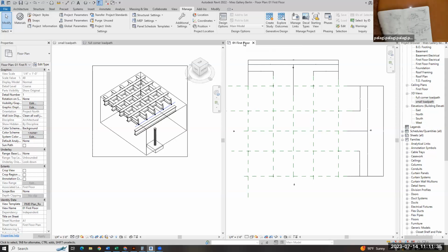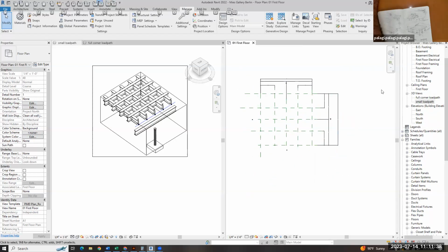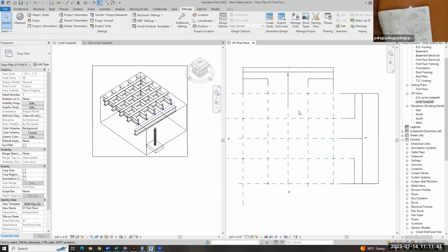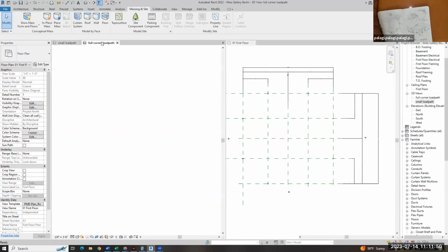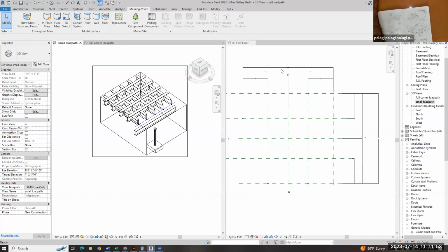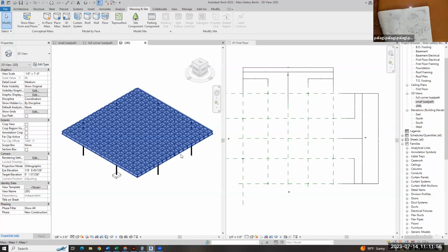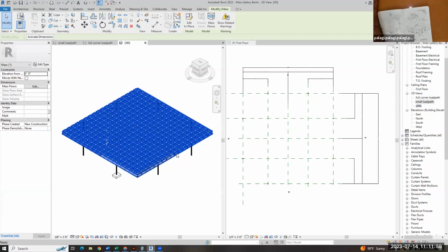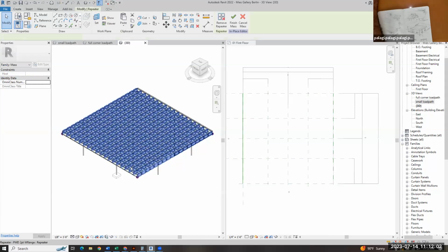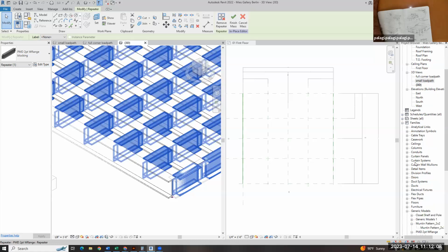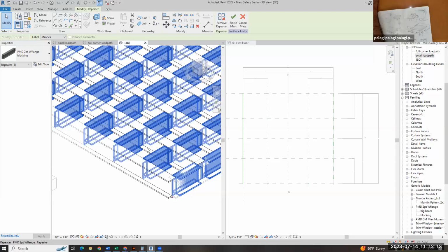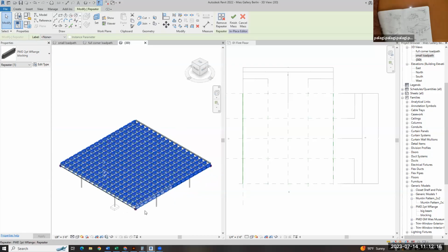what I did for this project was I started in the first floor plan and I roughed out my reflected ceiling lines. I then created a massing in place, and I drew a plane which I subdivided, and then in that plane, just like we did with the conceptual mass, I ran short ones one way and long ones the other. I renamed them the same way we did in our tutorial with big beam and blocking, the extensions. That's exactly how I did it for the whole thing.